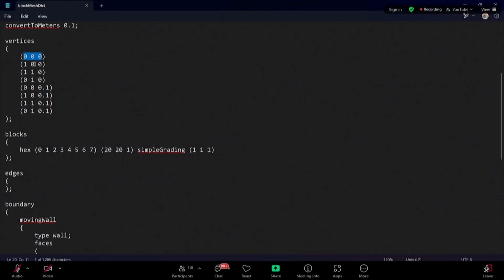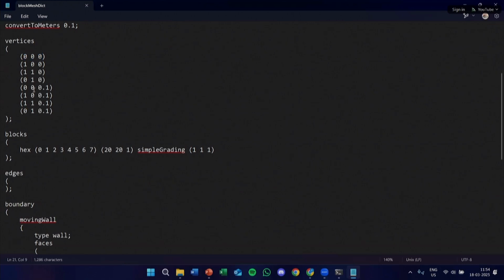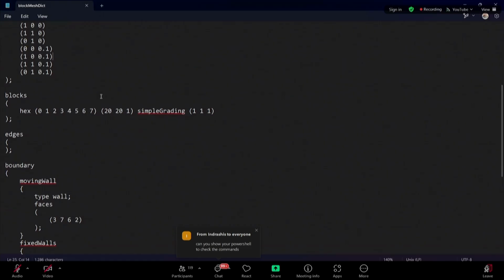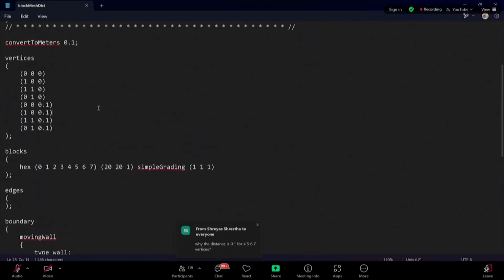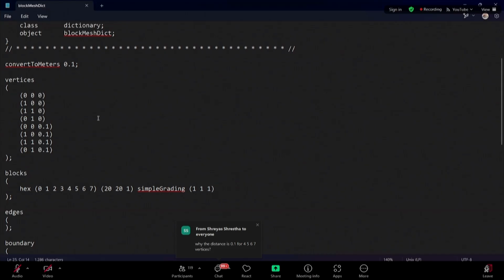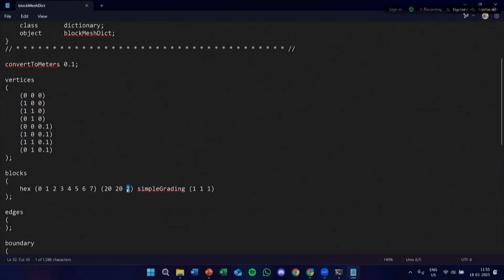So over here, you're specifying in your X and Y plane, and then we want the same replication in the Z direction, that you're giving it a minimum 0.1 distance, since we are only doing it in 2D. Thank you. So that 0.1 has nothing to do with the geometry size? No, you can give it as 1 also, because it won't make a difference, since in the Z direction we are only specifying 1 cell. So it is either way not going to compute in that Z direction.